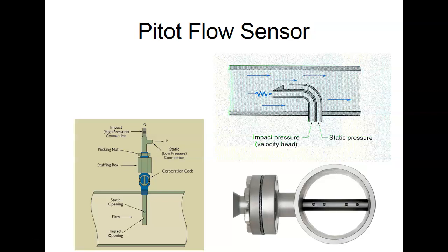These are pitot tubes. These I've got a lot of experience with. These were one of the speed indicators that we use on airplanes. So if you ever get close to the nose of an airplane, you see these two L-shaped tubes coming out pointing toward the flow. And basically, what you have to do on pitot tubes, you have to compare it to something. So what we do is we have one we call the static pressure. So this would be static right here, and then we have one that's the dynamic pressure. And then what they do is they compare the two.